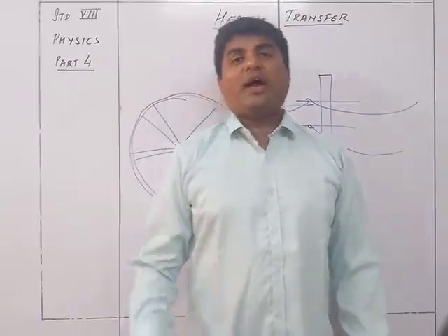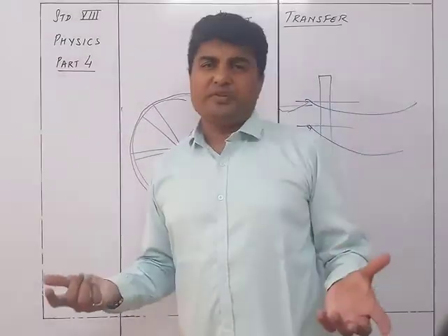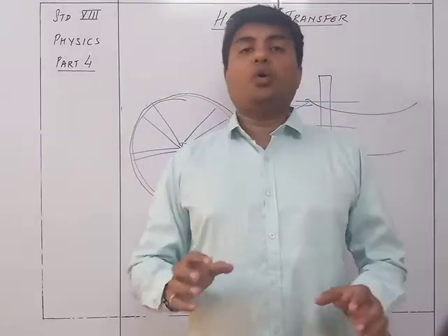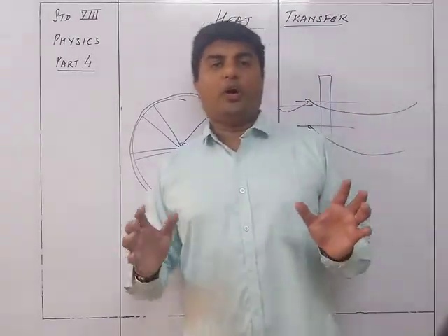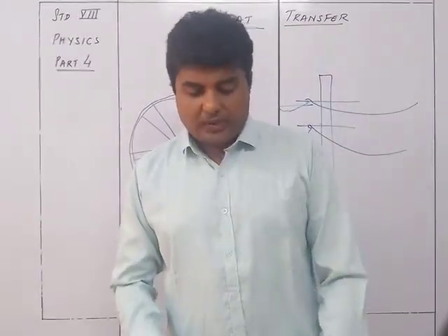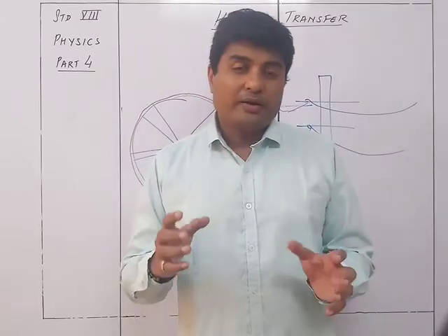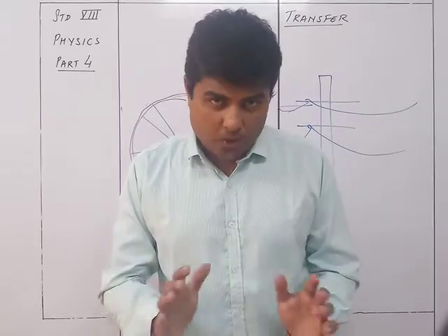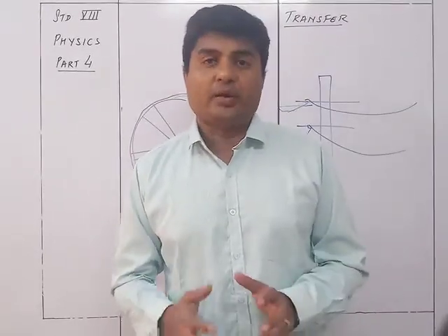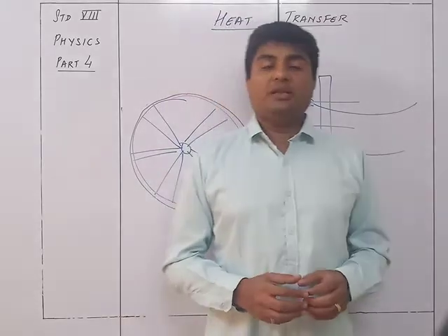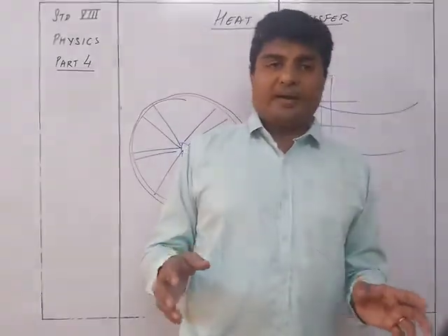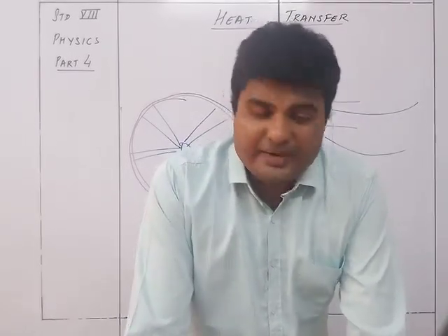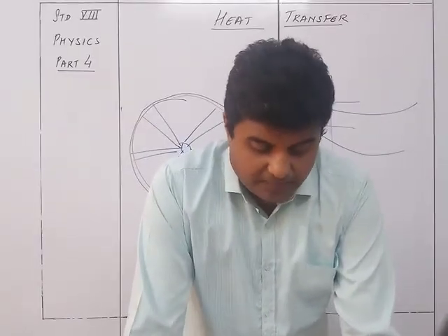So, we cannot have a linear expansion or a superficial expansion in case of the liquids, because it has got only, see, volume of this thing is going to be standard. So, liquids do not have a definite shape, but they have a definite volume, and because they have got only a definite volume, therefore the kind of expansion that can take place in case of the liquids will be only volumetric, that is cubical expansion. So cubical expansion is the only thing that can take place in case of liquids. But of course there are exceptions.